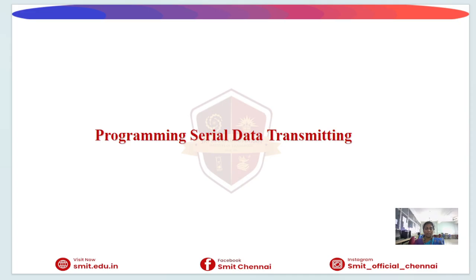In this session, we are going to discuss programming serial data transmission. In this slide, we are going to study how the 8051 microcontroller transmits serial data. Serial communication means sending data one bit at a time through the transmission pin. The 8051 uses UART communication to transmit data serially.